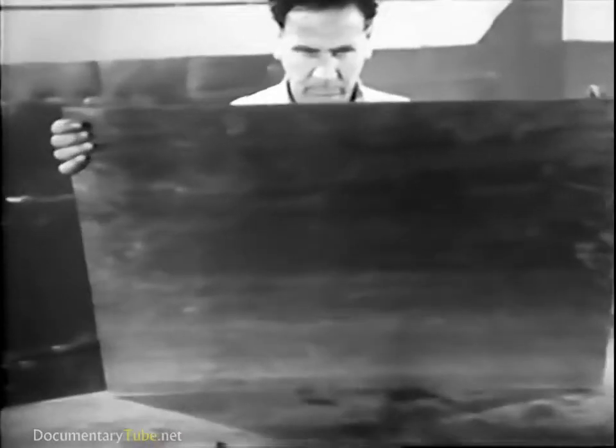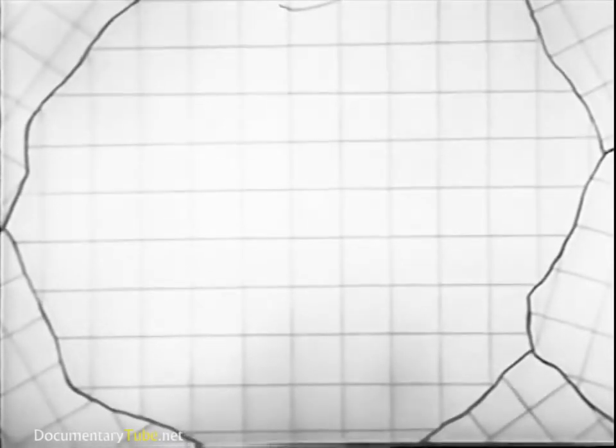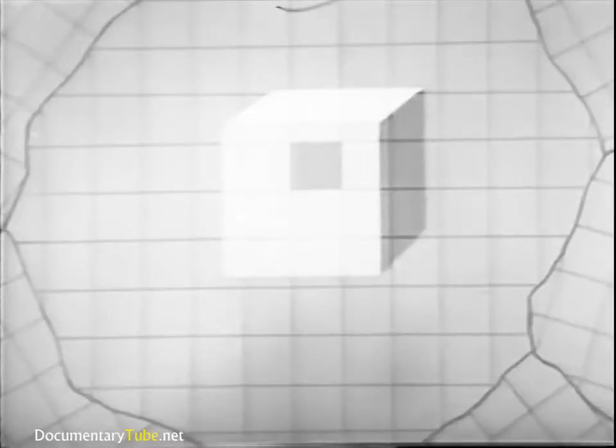These operations result in strain hardening or strengthening of the metal. The basis of this lies in the aluminum alloy itself. Microscopic study of a cross-section of an aluminum alloy specimen reveals a network formed by the boundaries between grains of the metal. Each grain is an accumulation of individual crystals or unit cells. Single crystal or unit cell movement may take place in the aluminum crystal. Through such movement, a crystal may undergo two types of deformation.